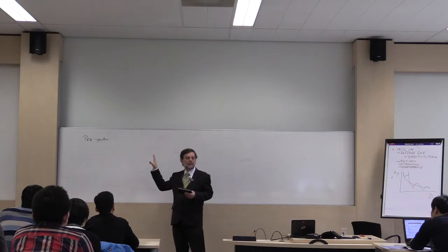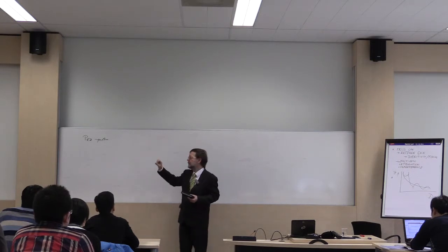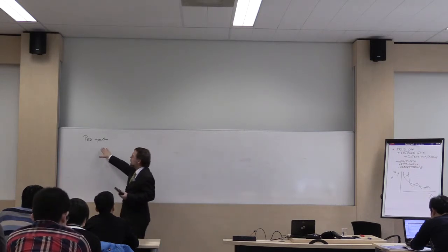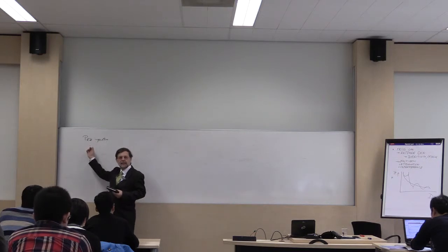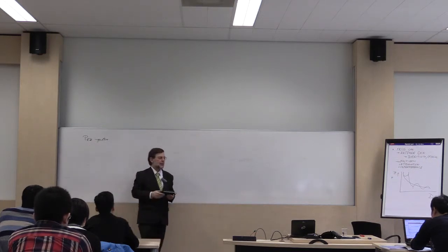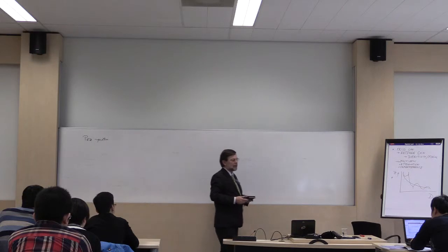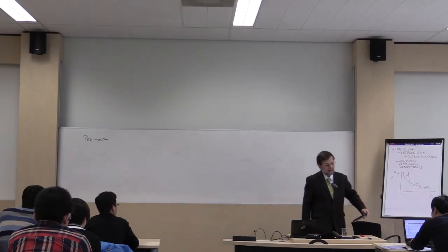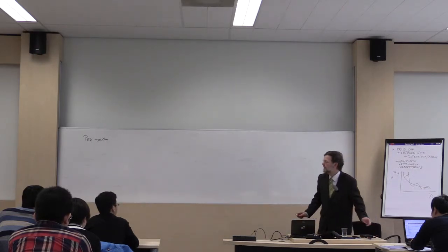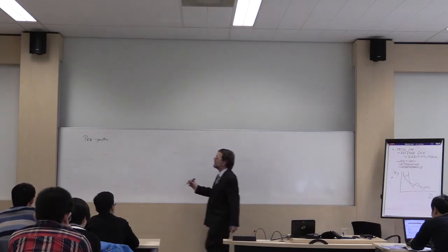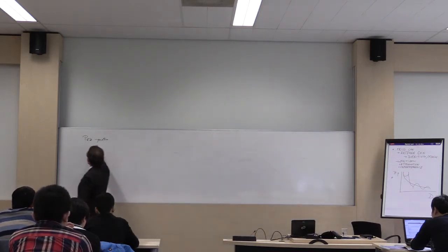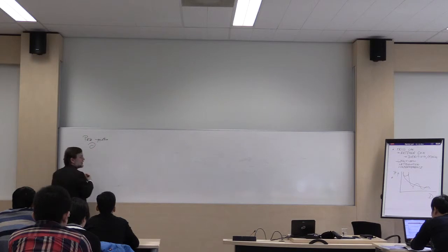But that doesn't help. For defining sensitivity, we need to know how to define that a signal is still being received or not. And one way of doing that is that in addition to the sensitivity at the input, the received power, you say, I have a certain quality of the received signal. And that can be, for example, the signal-to-noise ratio.